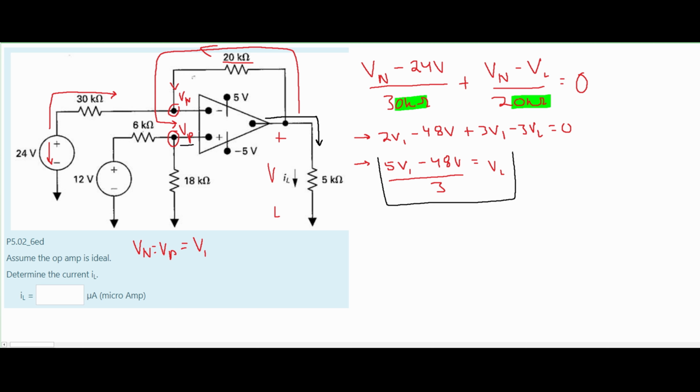We're looking at this Vp part. We know our voltage, we have some going like this. So we are going to have Vp, and the arrow I just drew is not the actual direction of the current. I'm just showing the relation of our Vp to this 12 volt source. So we have Vp minus 12 volts, and this is all happening over the 6 kilo ohm resistor. We have a plus because we have this 18 kilo ohm resistor that our Vp is also over.